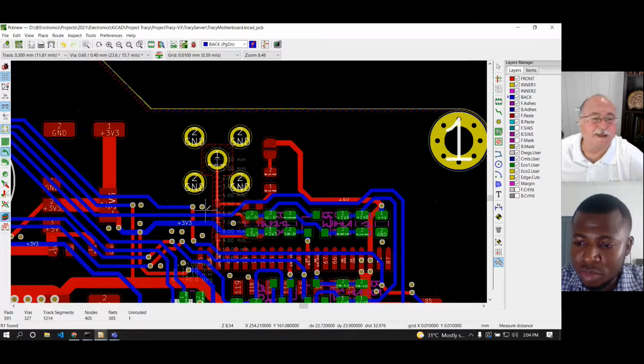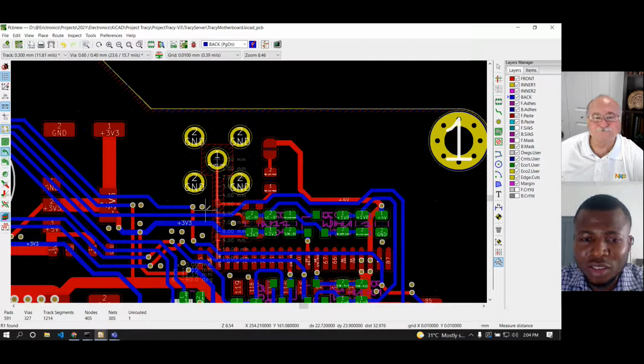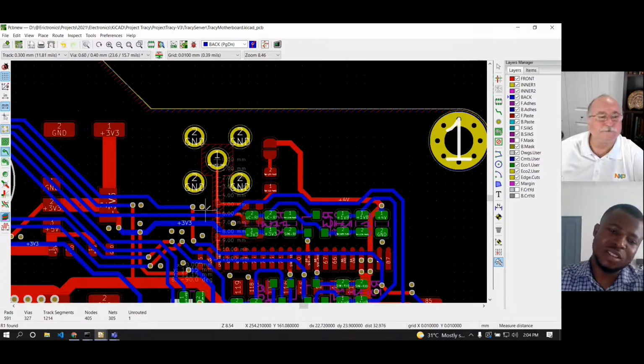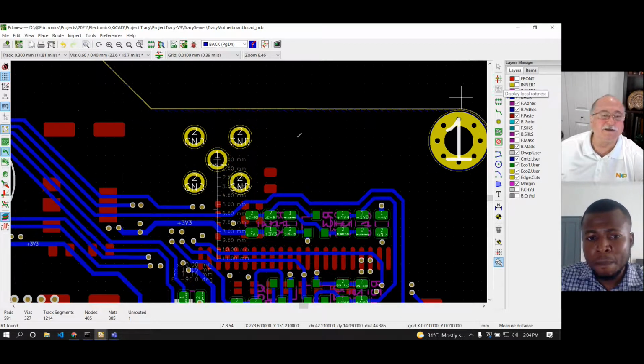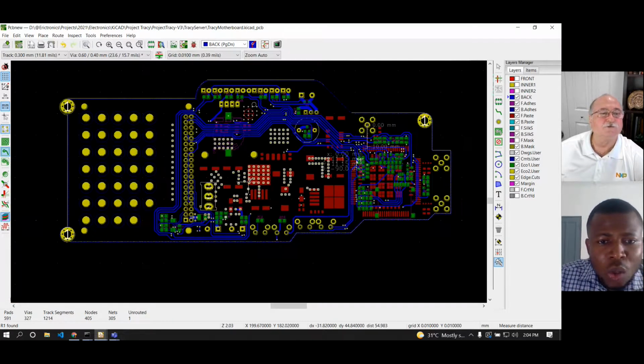And then when you go to fabricate your board, you want to also specify which of these traces are 50 ohms. Then they will make sure to adjust the process to manage those impedances for you. One more trick. Your last check will be to look for orphan vias on 4, and to make sure that you don't have any copper flood underneath any of the series components: resistors, inductors, capacitors.